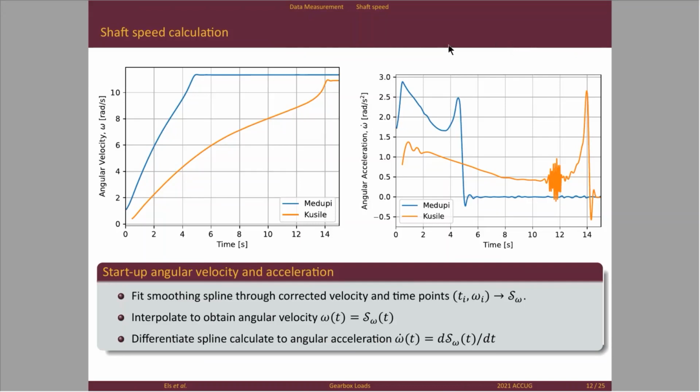The point that I want to make is that it's not really a soft start in a mechanical sense. It might be for the electric current and so on, but mechanically, you don't win a lot with a soft start because the gearbox still experiences that huge startup torque.